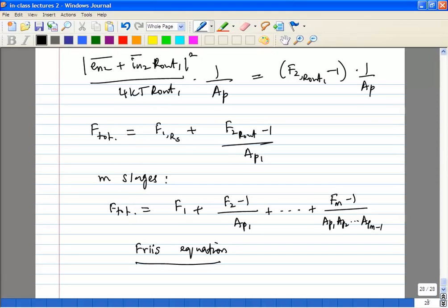So what do you understand from this? This is obviously the reason why you have an LNA right at the beginning of a receiver. Why do you need a so-called low noise amplifier? Because you want as much gain as possible with very little noise, so that the noise of the subsequent stages gets reduced by the gain of the preceding stages. Is that clear? Typically, when we get to mixers, you'll find that the mixer noise figure could be 10 or 15 dB, whereas the specification for the overall receiver chain may be only a few dB.